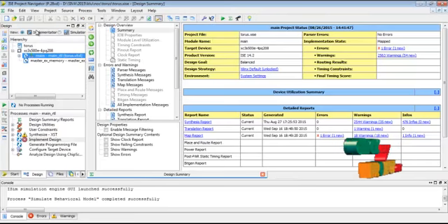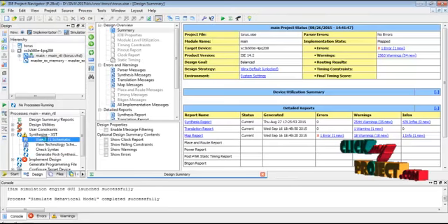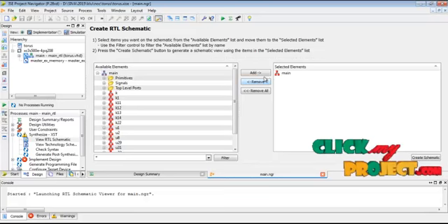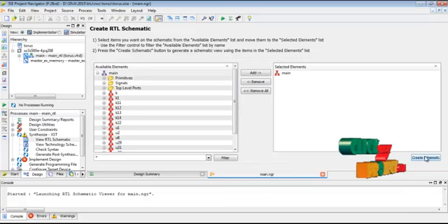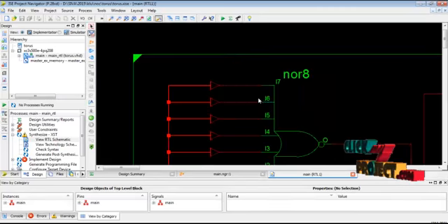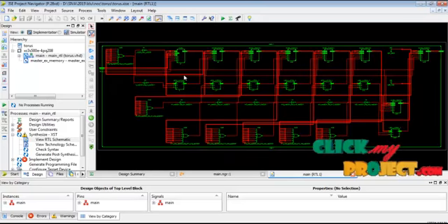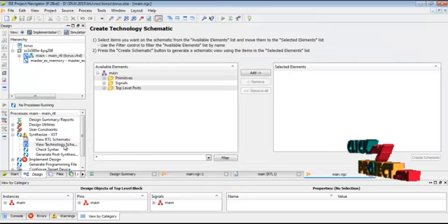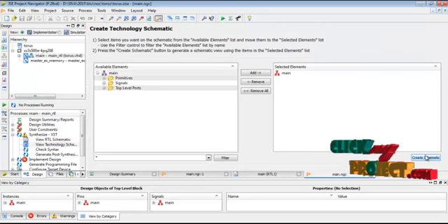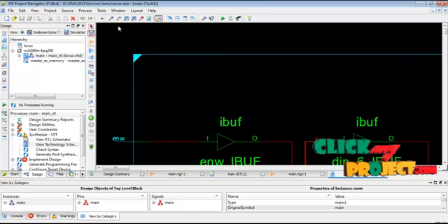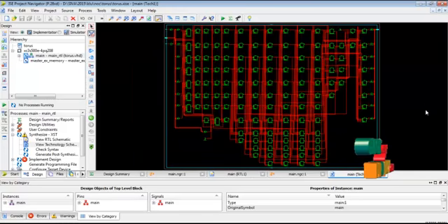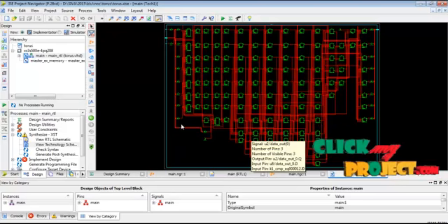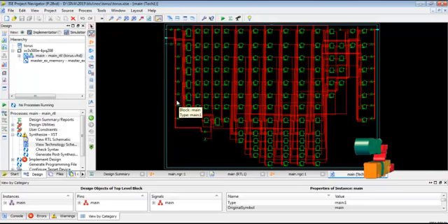Then we go to the implementation based process. The implementation process is used to identify the RTL diagram. The RTL diagram represents the logical blocks presented in our 3D based NoC architecture design. This is the required logical diagram for the 3D NoC architecture design. Then we go to the technology schematic. The technology schematic represents the FPGA structure and design oriented process. These are the lookup table and flip-flop pairs, the input output, and the buffer element connections for our required 3D